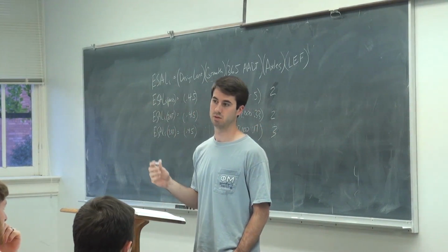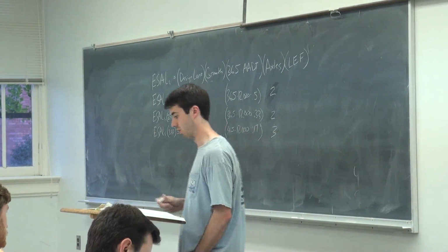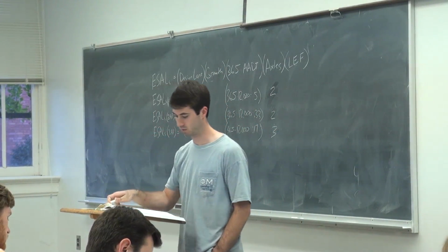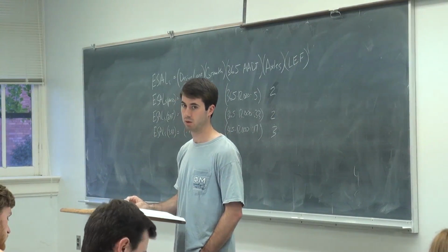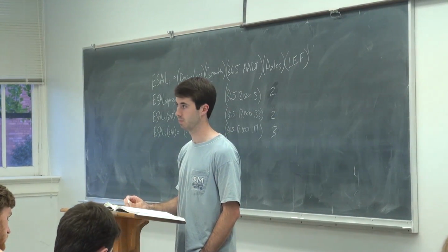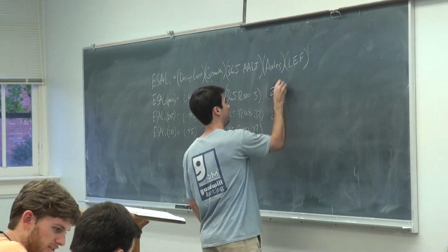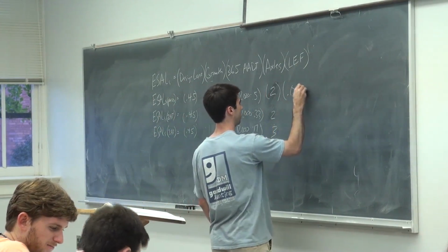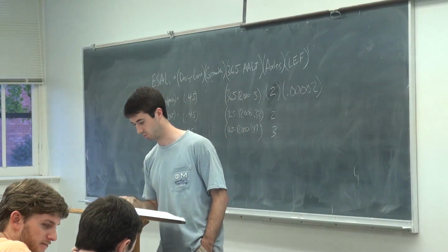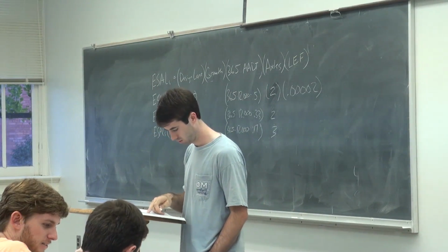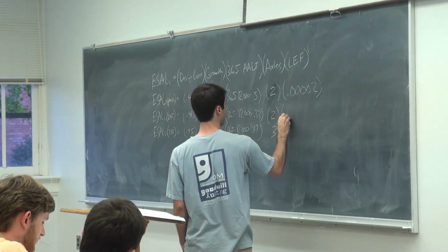You know how to calculate that? Yeah, that's where the handbook comes in. Alright, so for the passenger cars, we've got 1,000 pounds per axle. What is our load equivalency factor? 0.0002. What about for our two-axle trucks, which are 6,000 pounds per axle? Number?